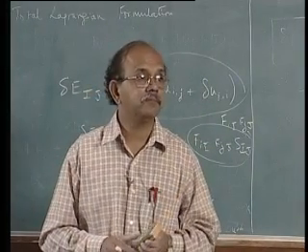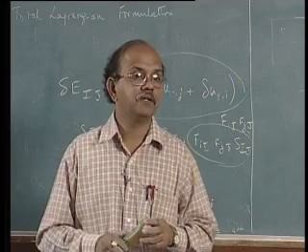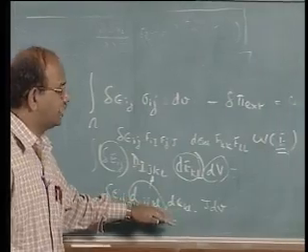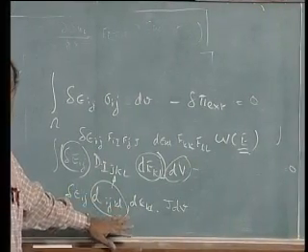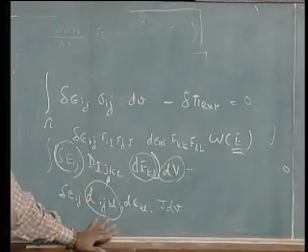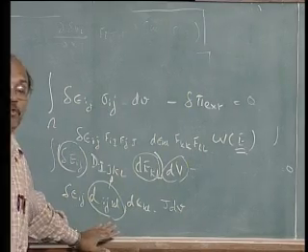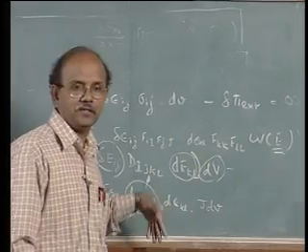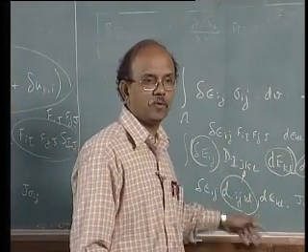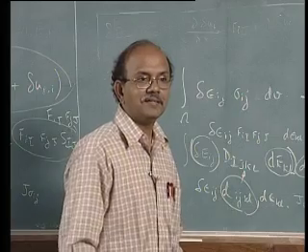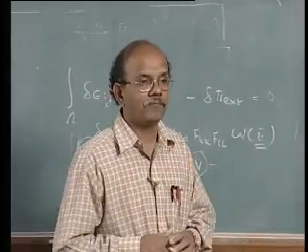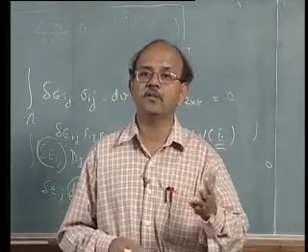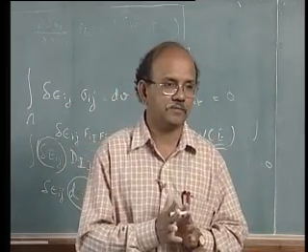But at the same time, please note that these guys here reduce to such a nice extent, and so close to the linear formulation, not only linear, even non-linear small deformation formulations, that the extension or implementation of the code from linear to nonlinear is very simple with updated Lagrangian.